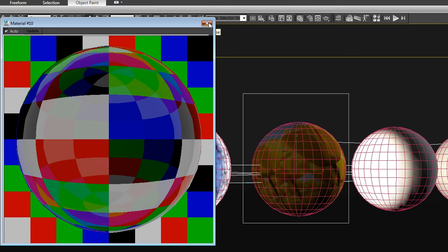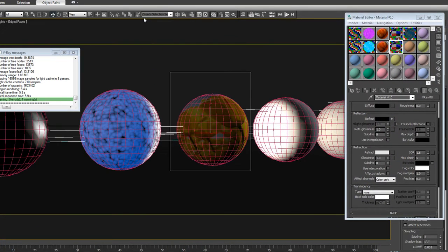So anyway, especially if I'm making glass railing or something that has butt joints in it or something like that, I usually give it a thickness and leave the refraction here at 1.6. It reads much nicer.